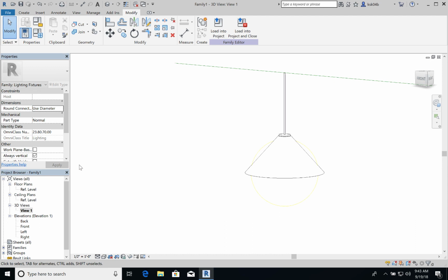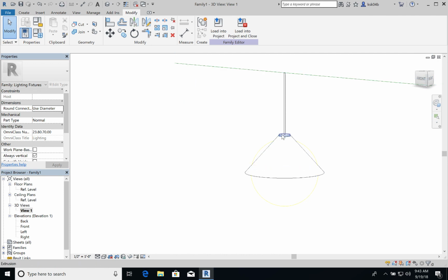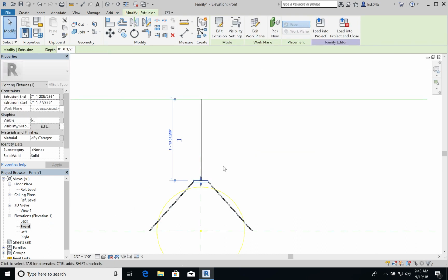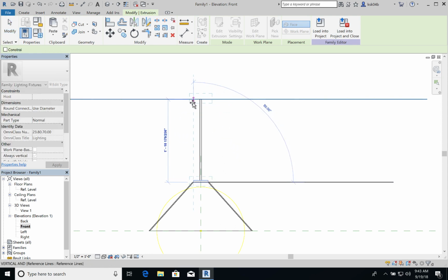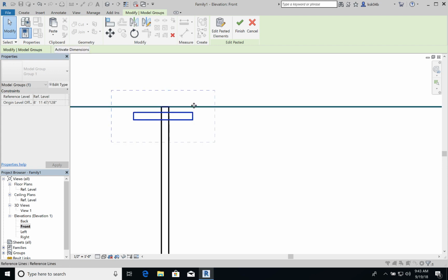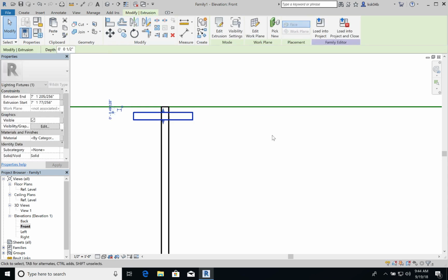So then what you can do here is another extrusion or a revolve at the top if you want to create your top plate, or you can simply copy this one and drag it up there, which is what I think I'm going to do. So I'm going to go to the front view. I will select here and hit Command C or Control C, and then Command or Control V, and then drag it up there. I want mine to actually be down where it's visible from the inside, the interior. So I'm going to click off of it and then select it again so I can have a more accurate selection point. So MV for move.